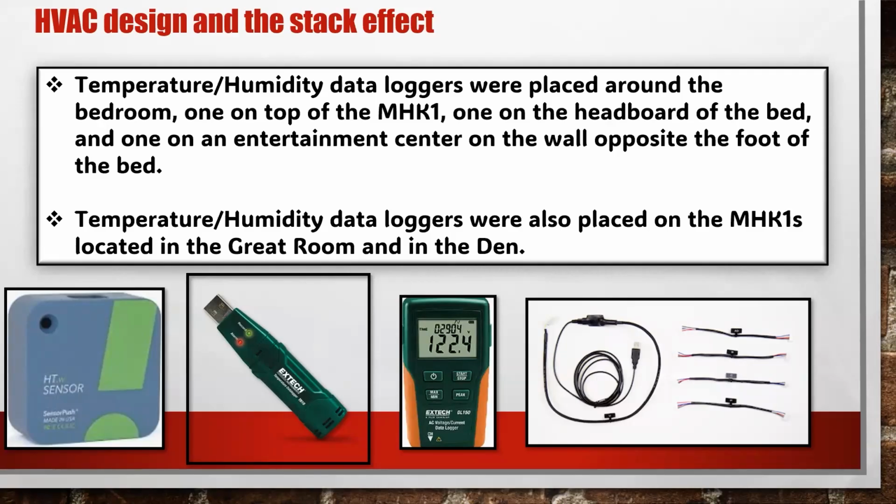Sometimes it would be better if you could do a small ducted unit like the SEZ and spread it over 3 bedrooms. A 9K spread across 3 bedrooms, 3K in one room, 2K in one, 4K in another, splitting the airflow properly, is a better option than putting 3 wall heads in those 3 rooms. But we still have to maintain 15 feet of duct on those, right? You said it can't do more than 15 lineal feet on those SEZ units, or is that not true anymore? It's technically true, provided you size the ductwork properly.